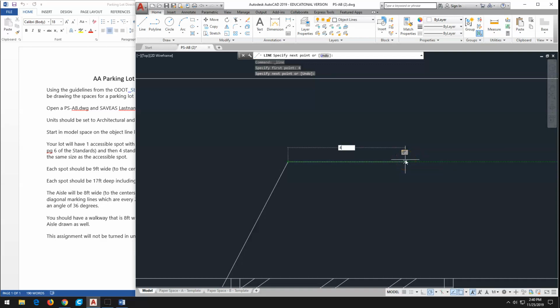You can measure it out so that it's exactly centered if you want to, and then we'll do the 4 inches there. Oops, I did it on the top part. So I might need a construction line there to be able to draw that part. Or I can just start at the bottom and match them up. So I'll go here, 4 inches, and just match it up.